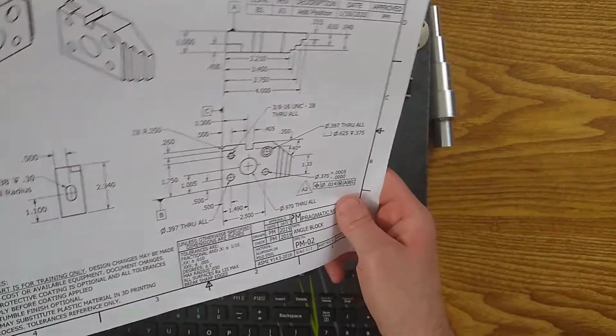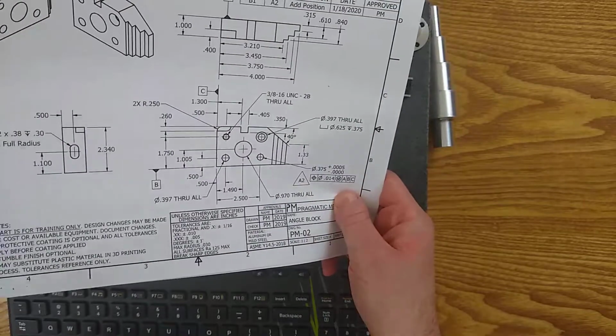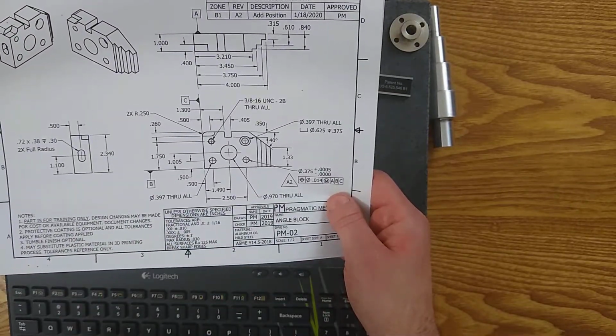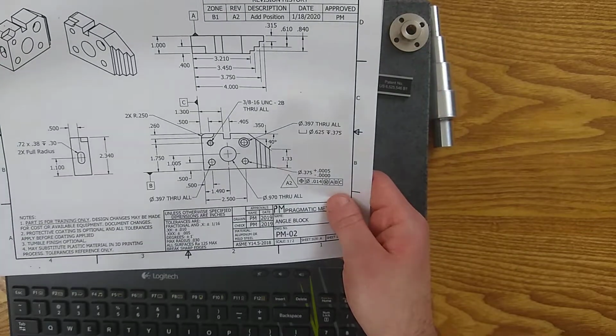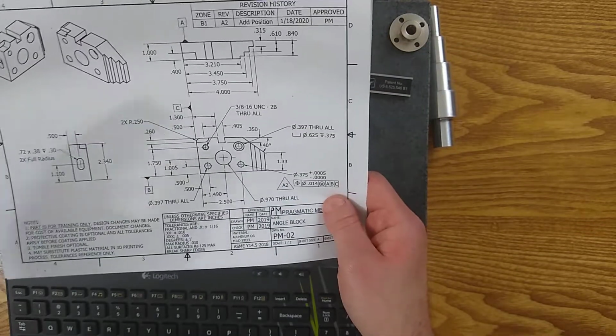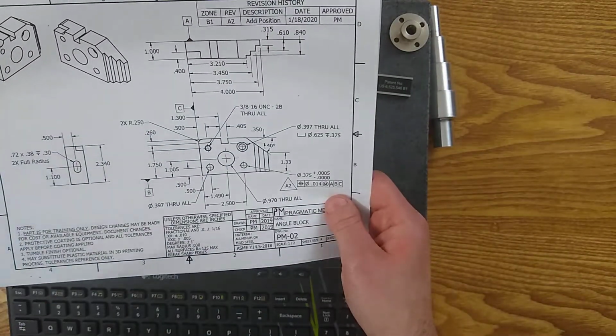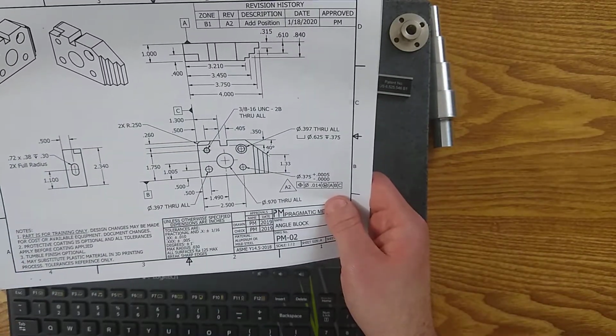When you get your blueprint, verify you have the right number of sheets and any other documents you might need. The blueprint or the router, job traveler, may reference other documents that you need to do this job. It may reference specific tools, additional instructions, additional requirements.